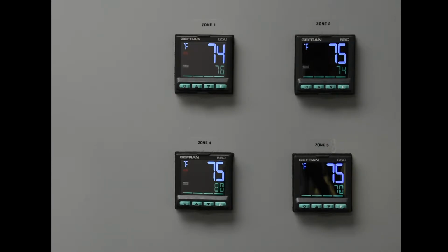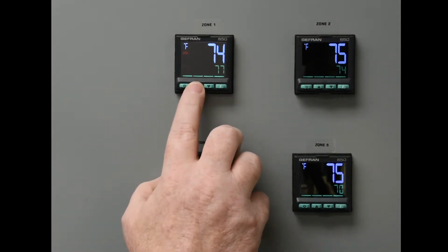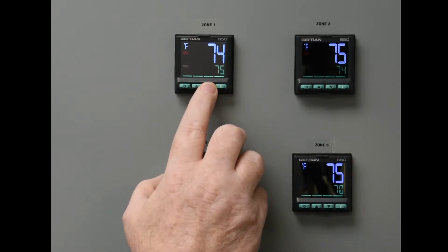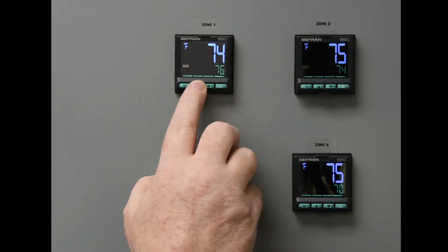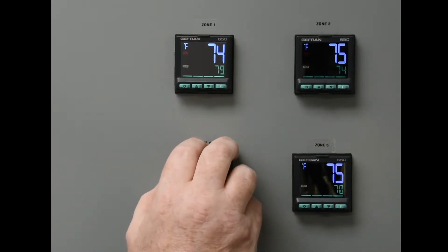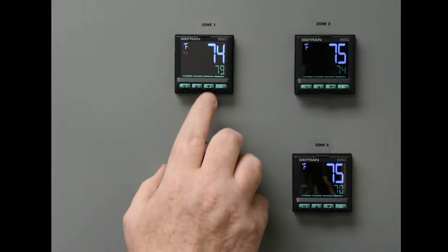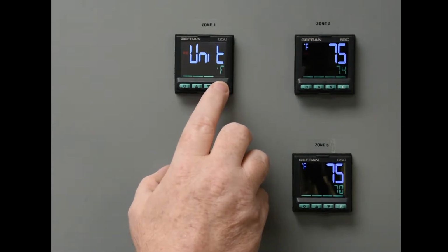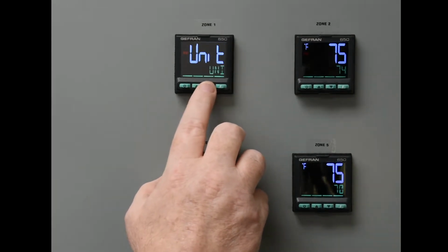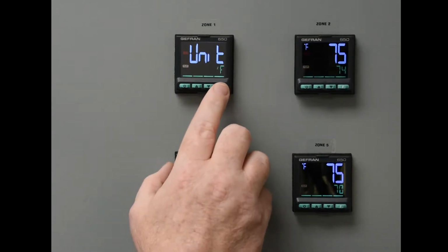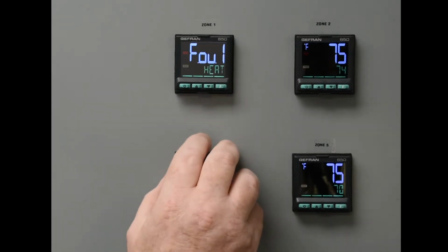Several settings can be made without requiring a password. To change the set point, simply depress the up or down arrow keys to change the set point. If the set point is higher than the present value, or the PV, you will see the number 1 in red on the left to indicate power to output 1, which is the heater. Press the F key to display the units value. The arrows can be used to change from F, Fahrenheit, to C, Celsius, and back again. After making a change, press the F button again to save the change.